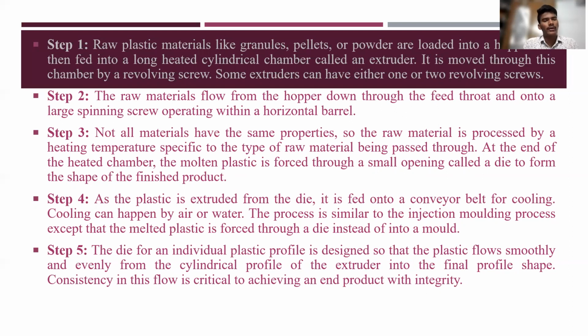And step 4, as the plastic is extruded from the die, it is fed onto a conveyor belt for cooling, and cooling happens by air or water. In the basic diagram they show water, but instead of water they can also use cool air, that is our wish. The process is similar to the injection molding process.